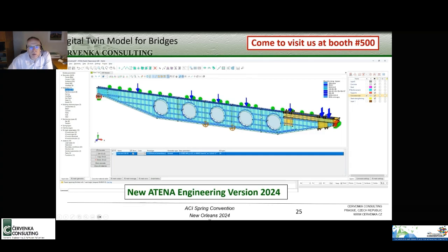Then some loads are applied, and boundary conditions. These circles indicate some monitoring points, because we would like to follow the deflections of the structure and the reactions, the total loads applied to the structure. Loads here you can see, the main load is by application of some distributed loading from the top.